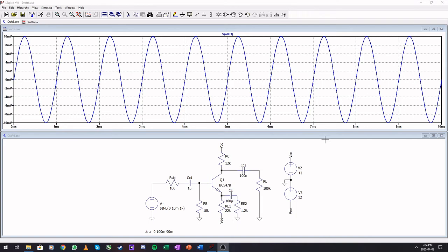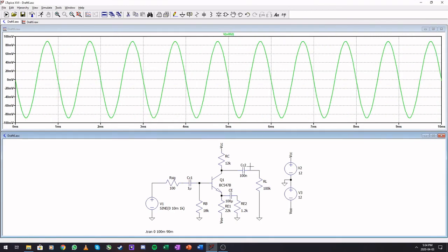For our FFT, we are going to use the same circuit that we used in the transient analysis, and we are going to start off by doing a transient analysis, which I've already done. And you can see that this sinusoid is to the eye quite pure, okay? And this input signal is kind of still small, so our circuit is acting in a linear fashion.